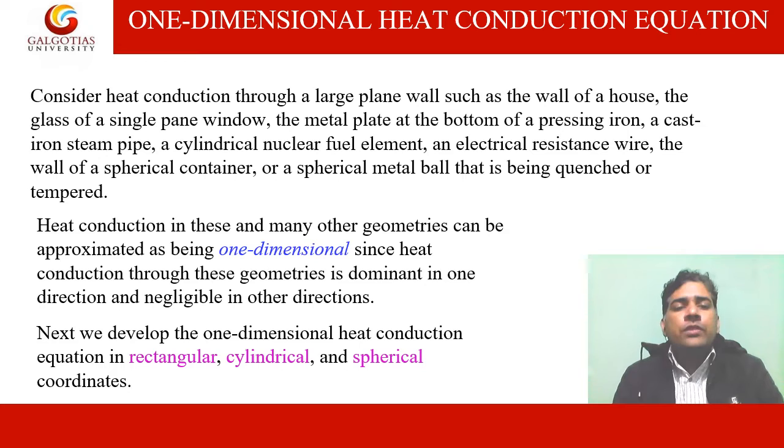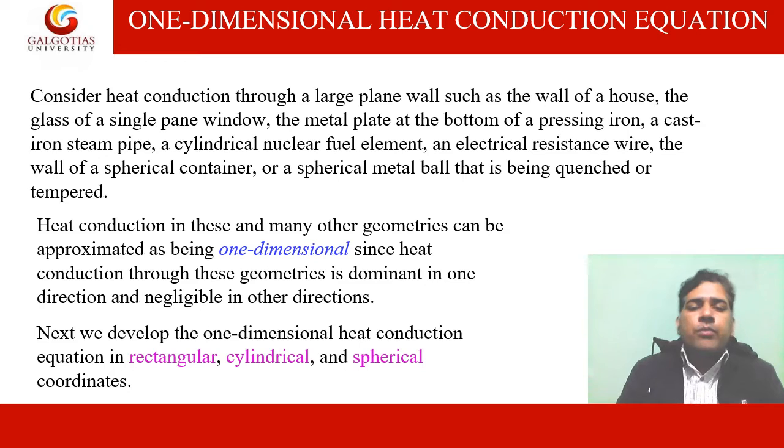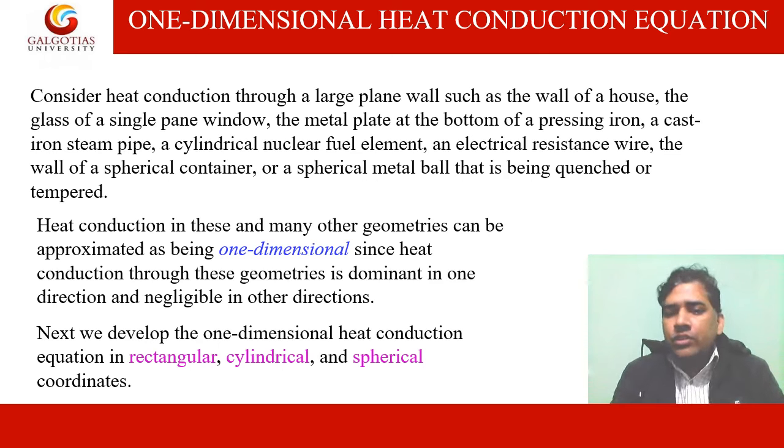Similarly, the glass of your single pane window, again the thickness is very small compared with the other two dimensions. That is why this heat transfer problem from the single pane window can be considered as a one dimensional heat transfer problem. So all these problems shown over here can be treated as one dimensional problems. Heat conduction in these and many other geometries can be approximated as being one dimensional, since heat conduction through these geometries is dominant in one direction and negligible in other directions.